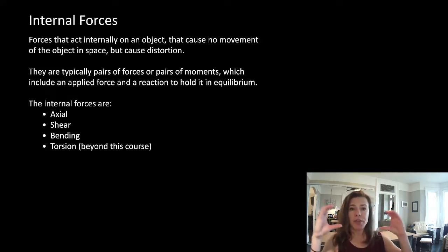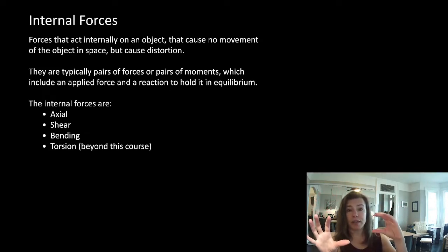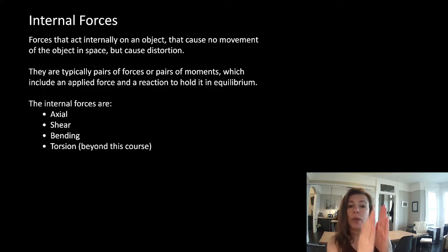We looked at the object as a whole, and then if we said, if this object isn't moving, if we put a piece of paper over this and only talk about this, we know it's not moving because the other half of the object is what's holding it in place. So if we thought about the other half of the object as the reaction, we should be able to figure out what those internal forces are on that. So we were able to do that pretty easily with axial loads. Axial loads are always a great place to start.